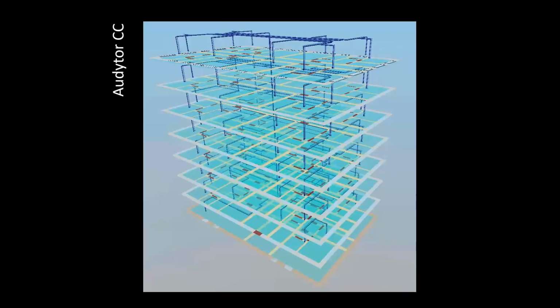When we design the plan views, we really create only in this method the 3D model of the building. I think it's very important because our reality is a 3D reality. It's also very often nowadays demanded by the investors. And also the practice shows that in 3D, you can see some problems, some collisions that you cannot see so easily in the plan view or any scheme, any diagram. So therefore, it's good to create the 3D model.